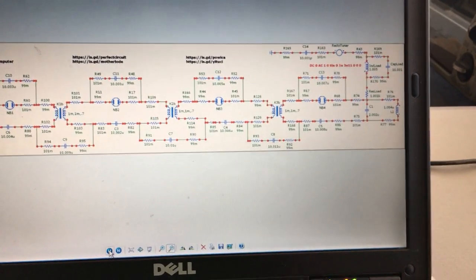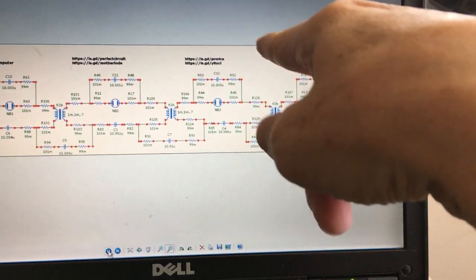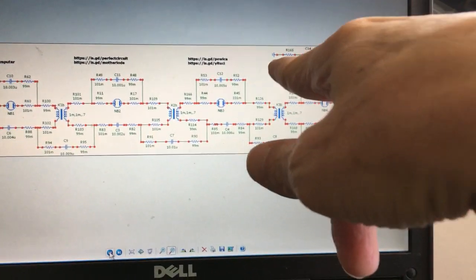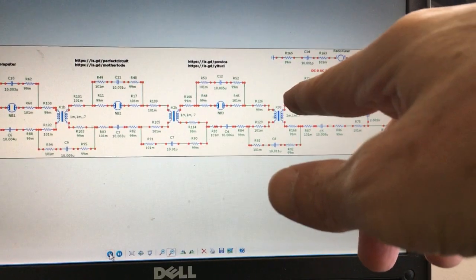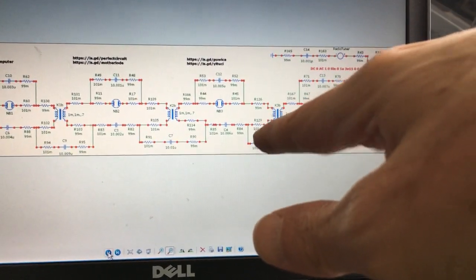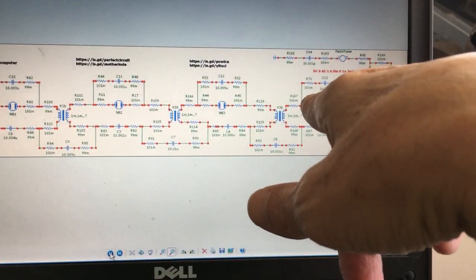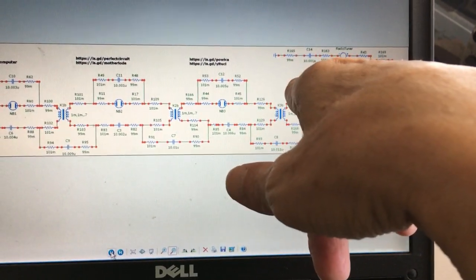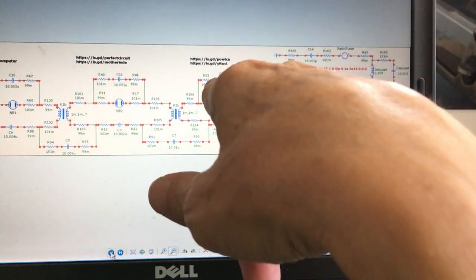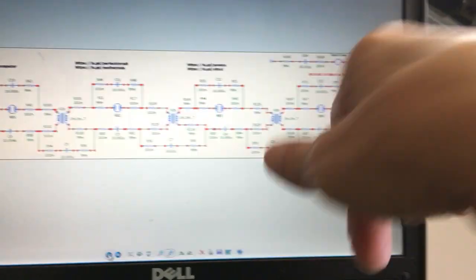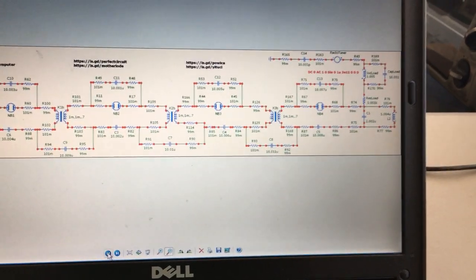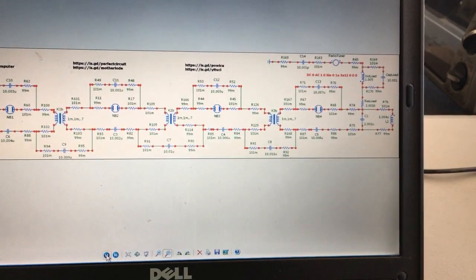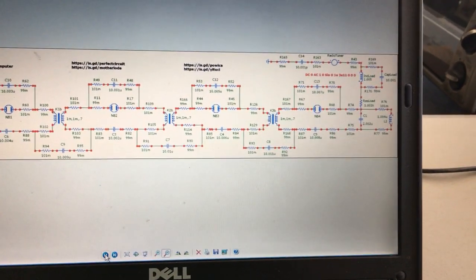So I'm going to try to steer away from that and instead move in the direction of a diode and a capacitor with a variable capacitance such that it's very low versus moderately low. You know, 10 microfarads is the minimum, actually, now that I think of it. So if I put a capacitor in here, even without a diode, of fewer farads than 10 microfarads, I may kill the circuit. So that might be the way to do it, is to use a varactor, right? A varactor, a variable capacitor, and you just dial it down, and it kills the circuit.